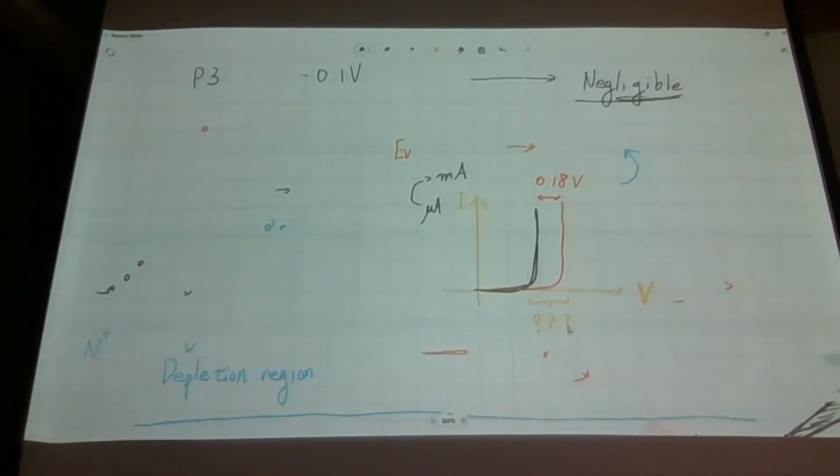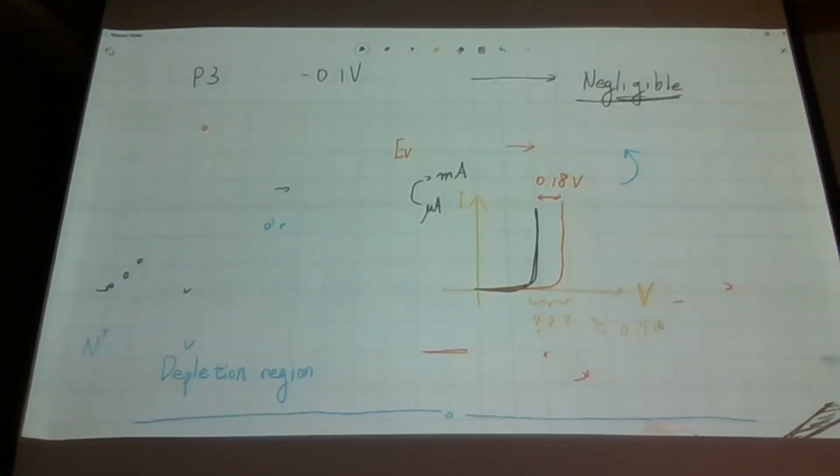So the typical number we assume in this course is about, for example, 0.7 volt or 0.8 volt. Of course you can ask me, why do we say 0.7 or 0.8? Is 0.6 acceptable? Is 0.5 acceptable? Well, then the decision should be made based upon our situation. We have no predetermined or rigorous definition for this value, but roughly, if we apply a certain voltage around 0.7 or 0.8, then this PN junction is maybe ready to conduct current.